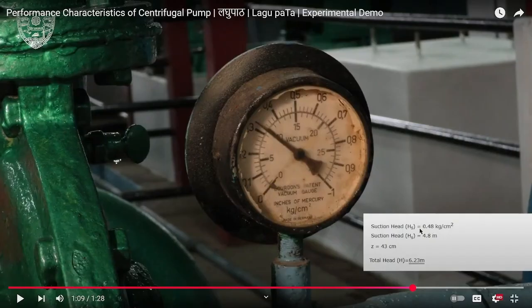If the suction is at a higher pressure compared to the discharge, then we don't need a pump, right? Fluid will flow from the high pressure region to the lower pressure region regardless of the pump. So this is the issue which I find this setup has. It could be that in the video they have made or the simulator that they have done, there is some miscalculation that they have put.